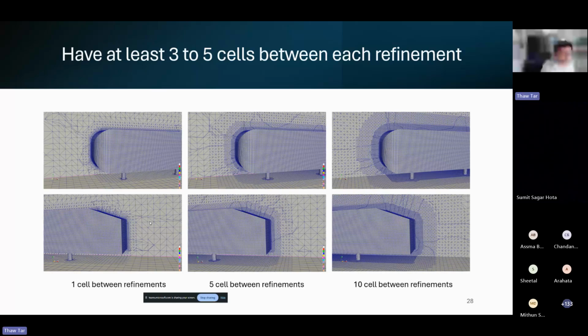Another tip is you can use ParaView to visualize even before doing any snapping. You can create boxes, cylinders, and spheres inside ParaView to visualize the location and range for your refinement regions, and then use their coordinates inside the snappyHexMesh directly. It will save you a lot of time.